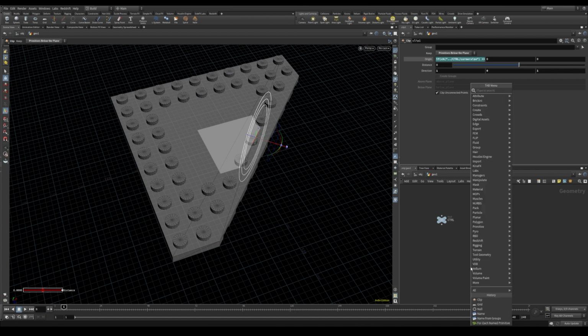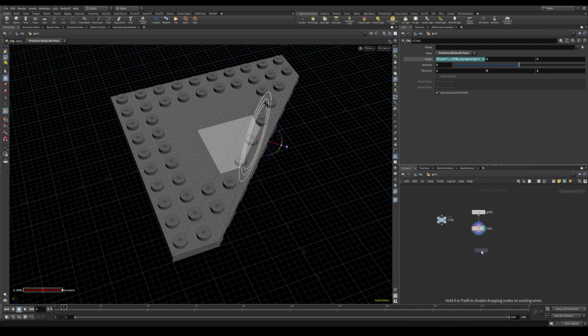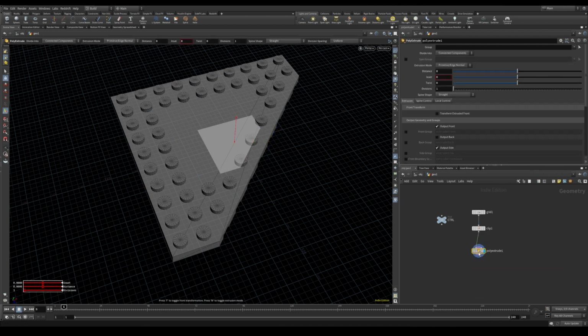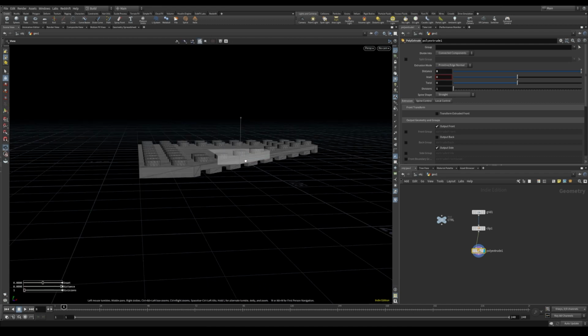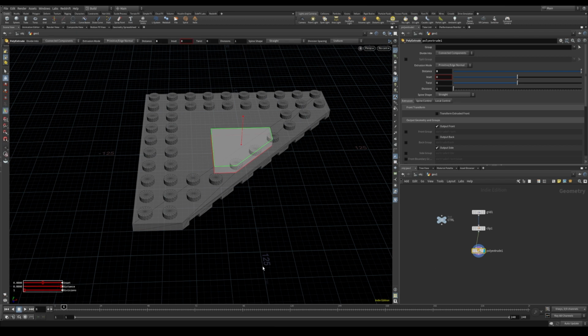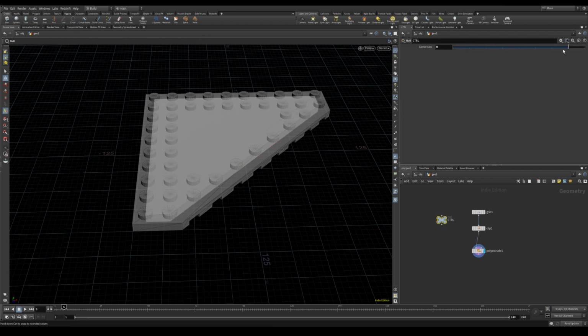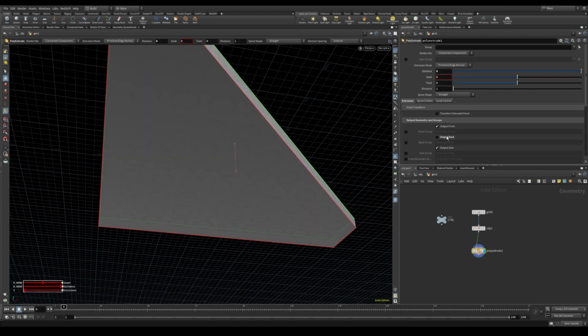So now let's add some depth to the pieces with an extrude, a poly extrude, and the depth will always be the same height, which is 8 for the scale I'm working to. So basically we don't need to do anything on the extrusion itself, but we want to enable the back group. Let's call it bot for bottom. So now we can do the inset part